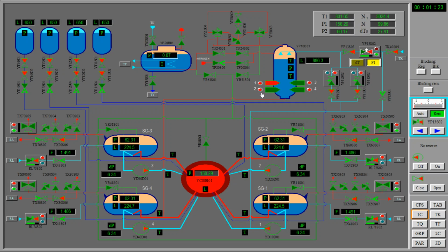Now we'll see as these automatic heaters turn on. These are electric heaters, so they receive energy from the electrical grid and heat up this water as we introduce cold water inside the pressurizer. When the water level starts to decrease, because we are just showering this with cold water, they will start turning on to keep this temperature not too far away from the primary temperature, which now is at 317 degrees. This is at 344. Okay, now they just turned on the 4-in-1s.